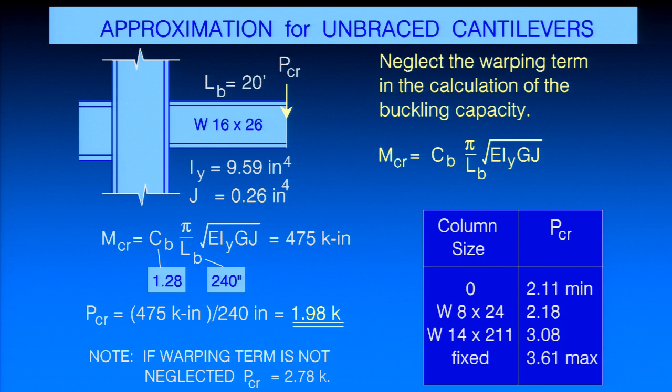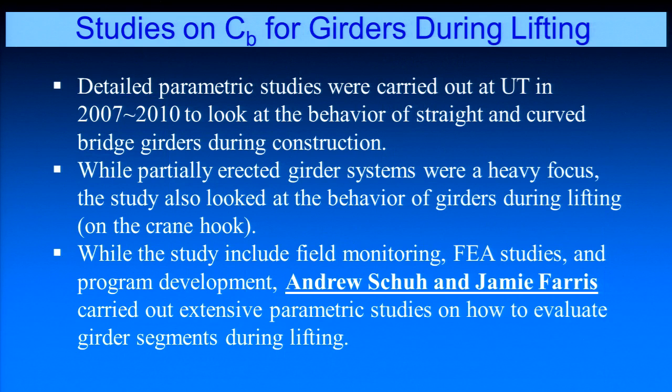This is one of the cases where, if you look at what's in AISC for the buckling solution, you almost have to go to Timoshenko's equation, which we include in a user note, to actually see where the warping term is and where the St. Venant term is. But it's an approach you can use on some neat problems.